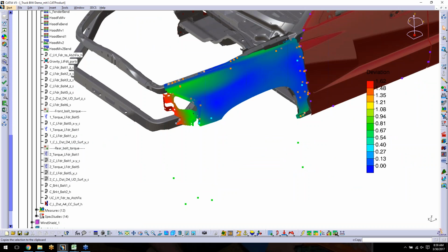So the model tells me that my second scenario, which was before, was better here, and my first scenario, it's better here. So if you drive this bolt first, you get better, less variation at the back. If you drive this bolt first, you get more variation at the front, basically. Okay?